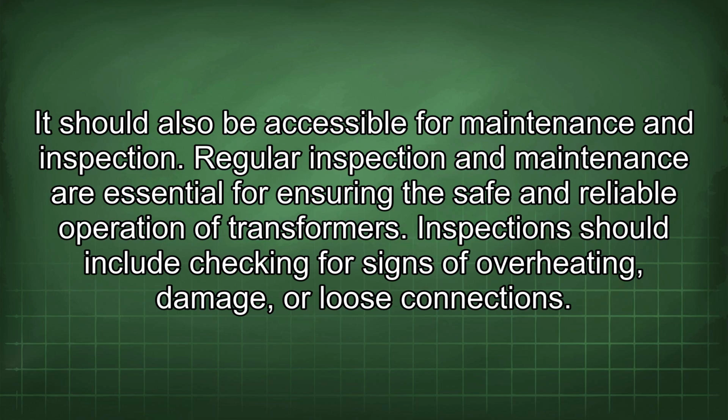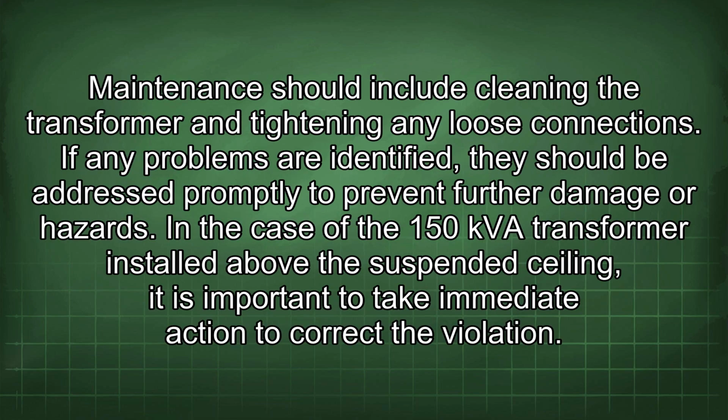Regular inspection and maintenance are essential for ensuring the safe and reliable operation of transformers. Inspection should include checking for signs of overheating, damage, or loose connections. Maintenance should include cleaning the transformer and tightening any loose connections. If any problems are identified, they should be addressed promptly to prevent further damage or hazards.